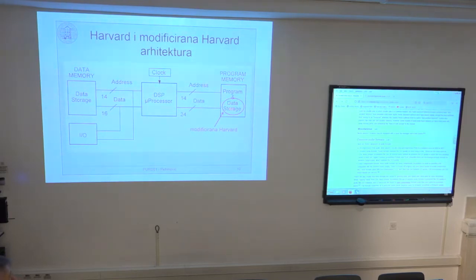In particular, I can fetch, for example, a filter coefficient from this program memory. And since these buses are independent, I have an independent address and data bus for data memory, and an independent address and data bus for the program memory. I can do this simultaneously.